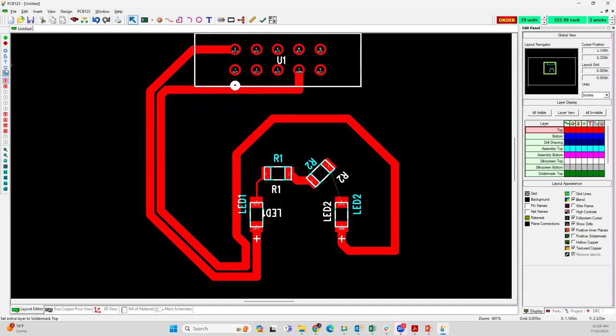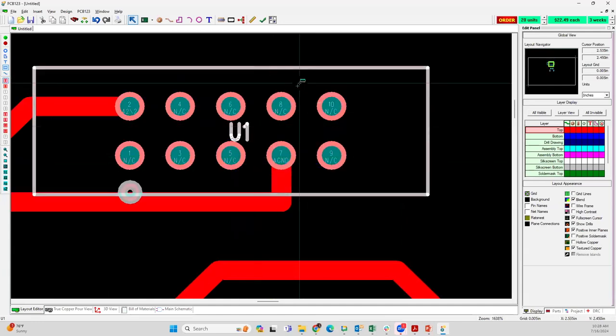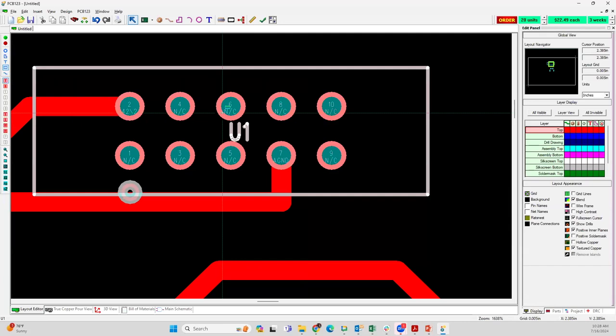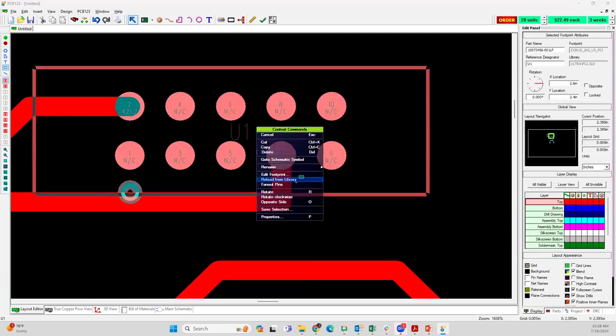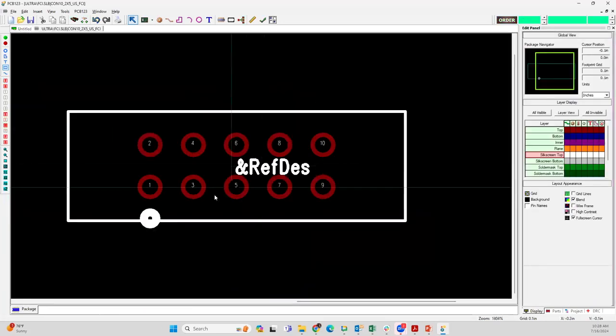And let's say an 8-pin connector is not available from this manufacturer or from DigiKey, but you need one, or you're going to trim a part that you just trim a bit off of it. So you say, okay, set my filter to parts. I'm going to go in and say, edit footprint. That's this right here. You get a whole new window, and that's just a footprint window.